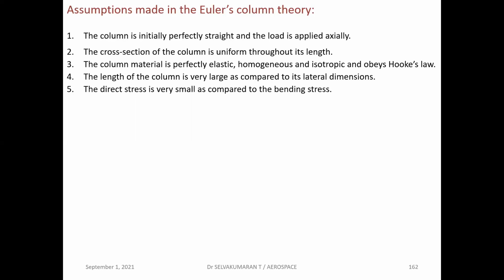So bending stress is something different, which you get from solid mechanics. M by I is equal to sigma B by Y. Sigma B is equal to M by I into Y, or M by Z, where Z is the section modulus. That is nothing but a bending stress.